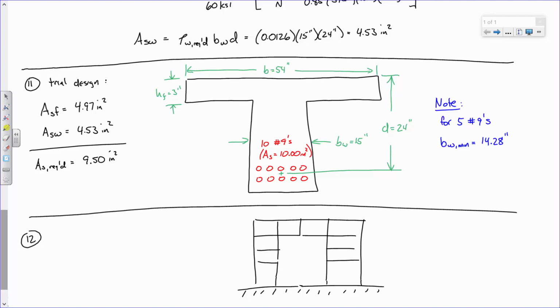One element in this building that the structural engineer is going to have to pay real close attention to is this one right here, okay? Because think, if this building goes up another few stories, that beam is going to have a boatload of load on it, right? Because it's got to hold up the rest of that building, okay? And so there's a name for this in structural engineering, we'd call that a transfer girder.